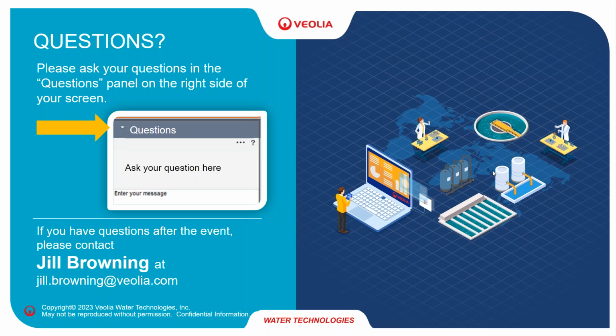And then there's some applications. What we find is the energy recovery device, as I mentioned earlier, really dampens the pressure variations. That's not so important at the lower TDS range, when you're running at lower pressures. If you have an application at low TDS and your recovery rate is, say, 90%, you're still only below 300, 400 PSI.